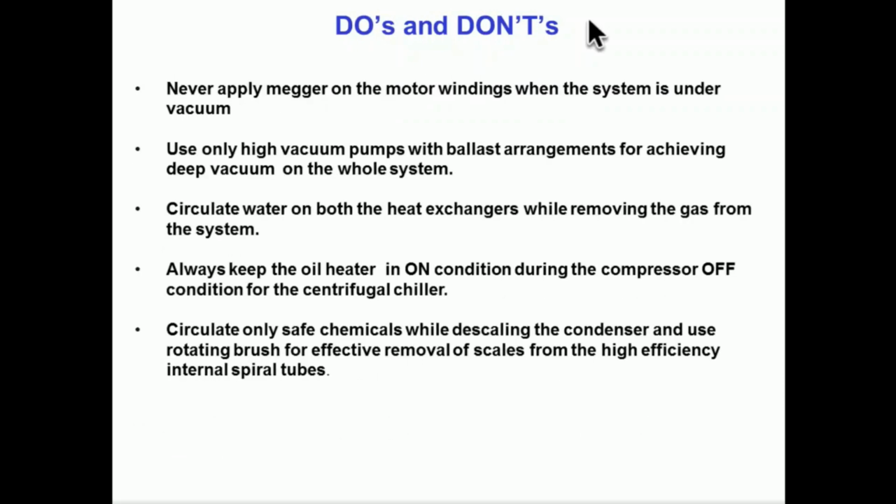Never apply a megger on a motor winding when the system is under vacuum, because you know the corona effect can happen. Use only high vacuum pumps with a ballast arrangement for achieving deep vacuum. Otherwise this can lead to the moisture level going beyond the specified limit. Practically, many times we have seen that because this practice is not being followed, the ppm level on the moisture is always higher.